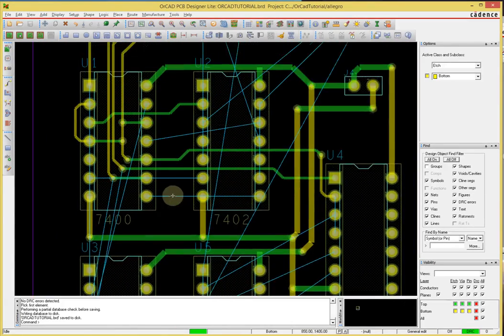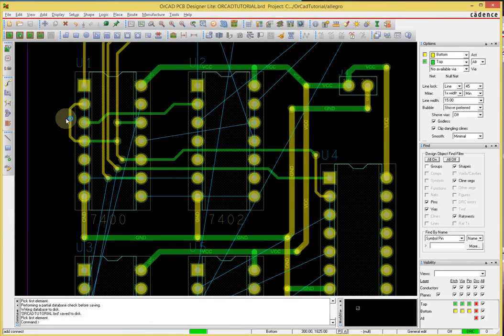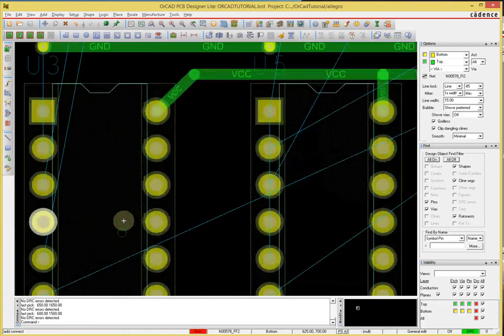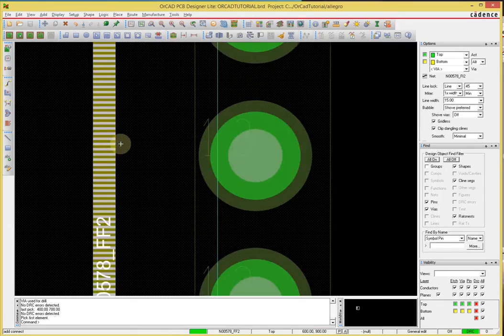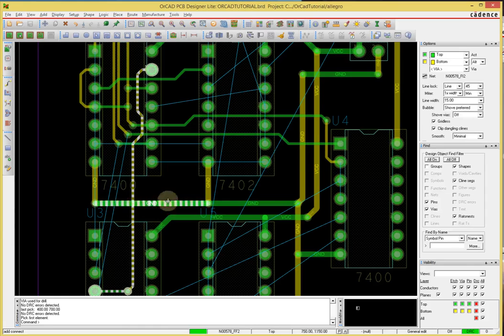Okay, we have some pins we gotta lay out, so let's just continue. Alright, F3, add a trace. I'm already in the bottom layer, and as I said before, I have room for one more trace in between here. Bada bing. Okay, we want to pan down. Alright, double click, connect. Okay, what else?